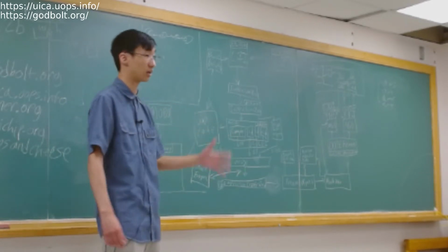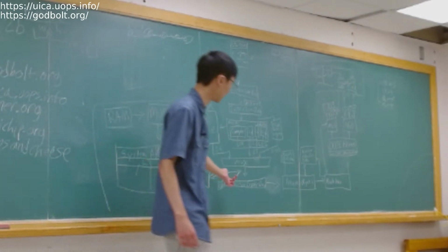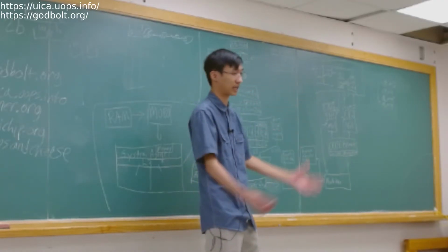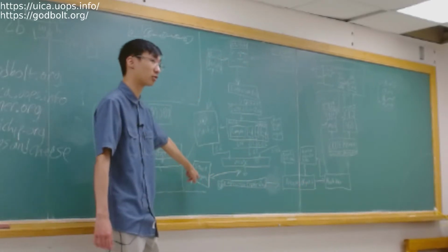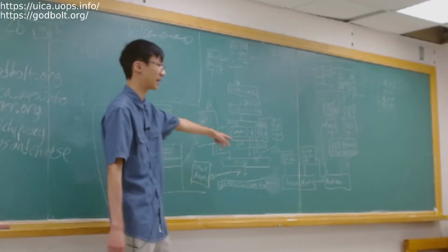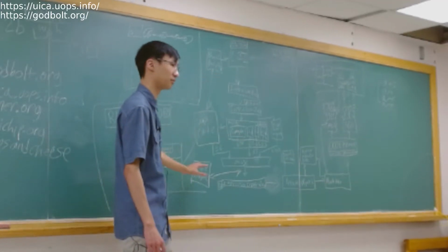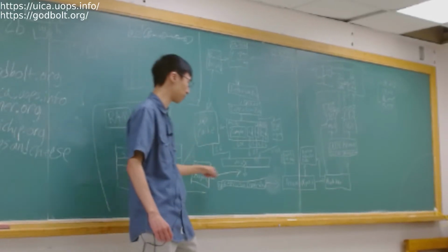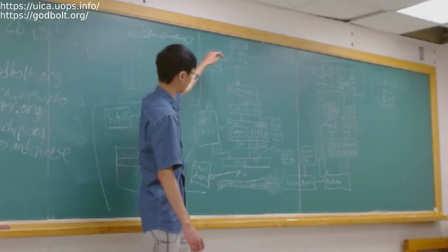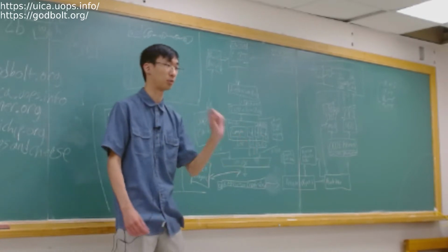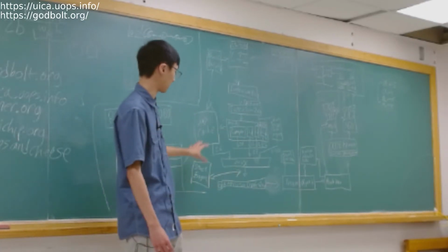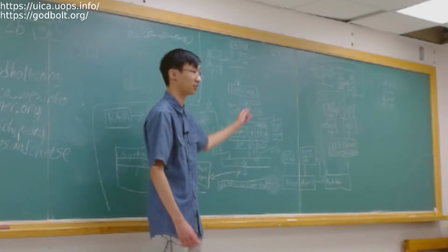And if you're modifying the stack pointer, I'm not going to wait for you to go through the whole entire chain to find out that the stack moved by 4 down, because I know it moved by 4 down. So I'm going to keep a counter that tells me how far up and down I am relative to the actual stack pointer. And the moment my counter saturates, I dump a UOP in that actually updates the stack pointer. Or if an instruction comes down that says read or modify the stack pointer, I'm going to dump a UOP in and modify it for them so that we can keep it in sync and also reduce the latency of it going all the way through, right?